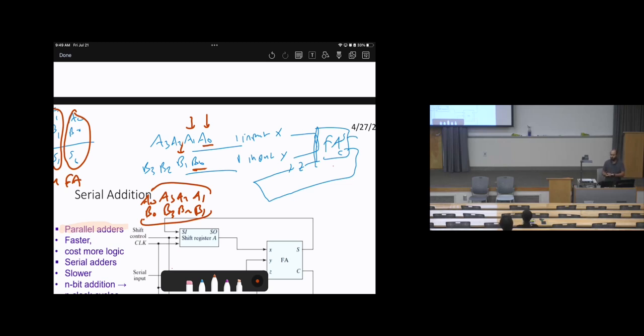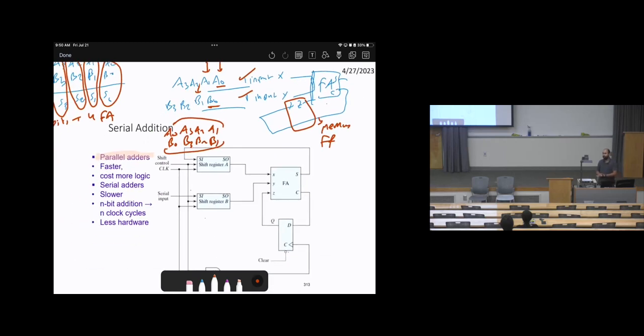And so make the sum. But this can be applied for input and output, X and Y. However, we also need something else related to the carry bits. If we keep the carry bit like this, it will be updated automatically. But our target is to hold this carry bit until the next cycle happens. Therefore, we need a memory element, which is a flip-flop. It can be either a D flip-flop, JK flip-flop, or T flip-flop. For example, in this example, we will use a D flip-flop.